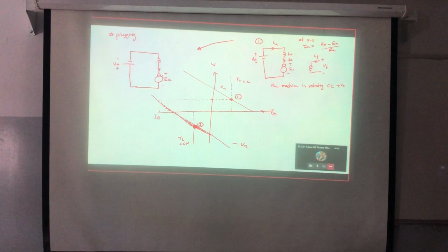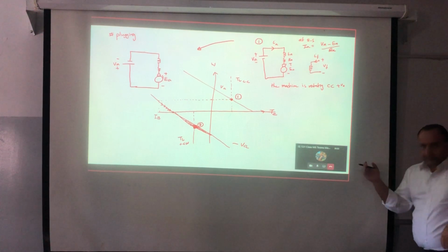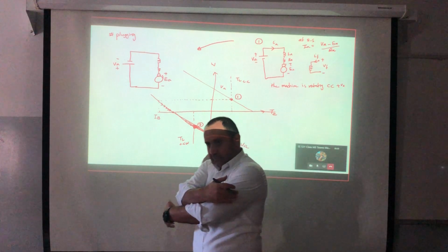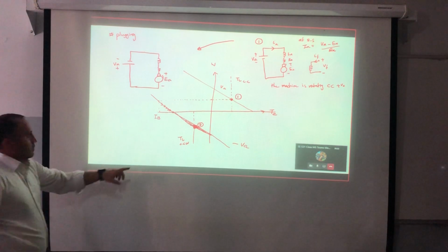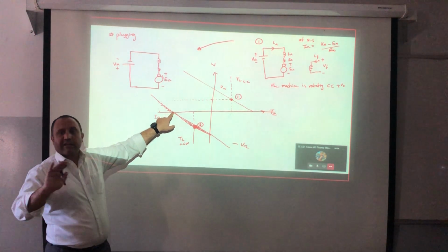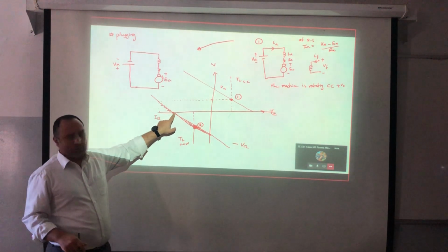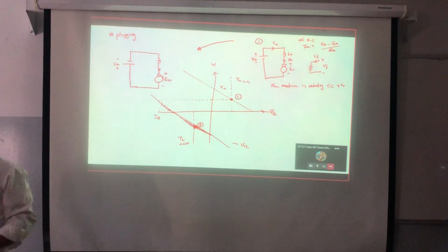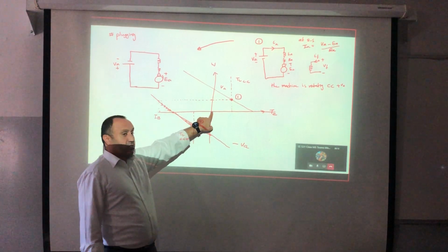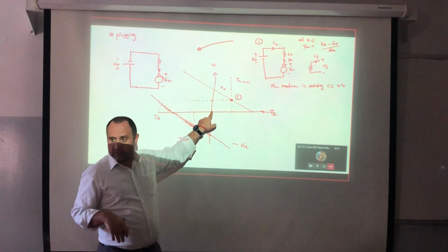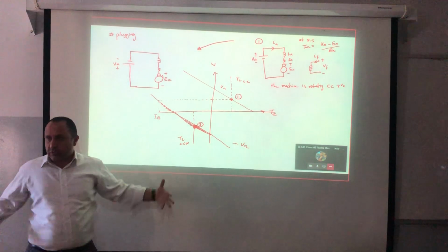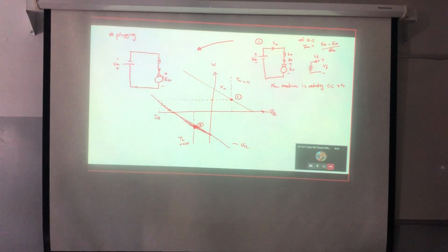Now here, if I disconnect the load and a mechanical drum is engaged, the machine will stop. Why? Because without a mechanical brake, it will never stop, since the machine has energy and inertia. At this point, 0 torque, 0 speed, to stop it I need to engage a mechanical drum or a mechanical brake.